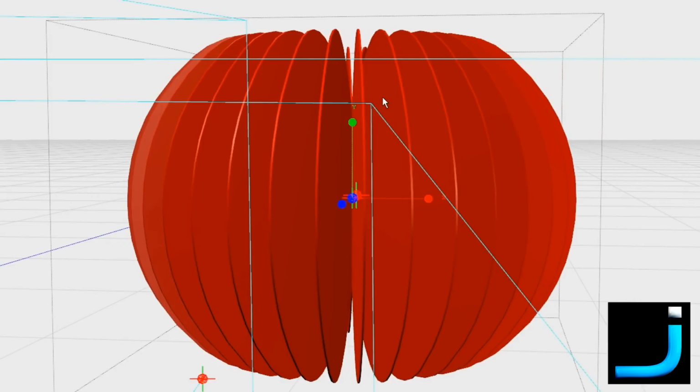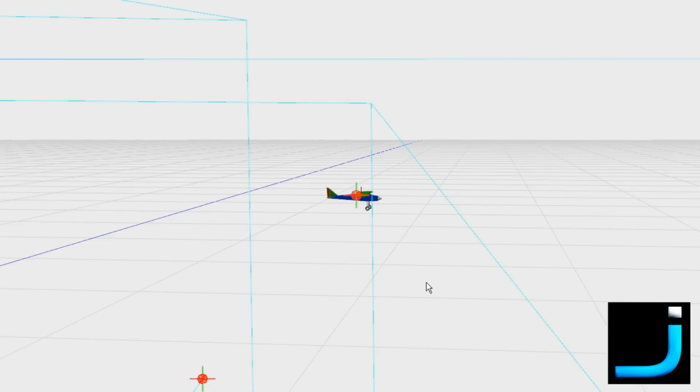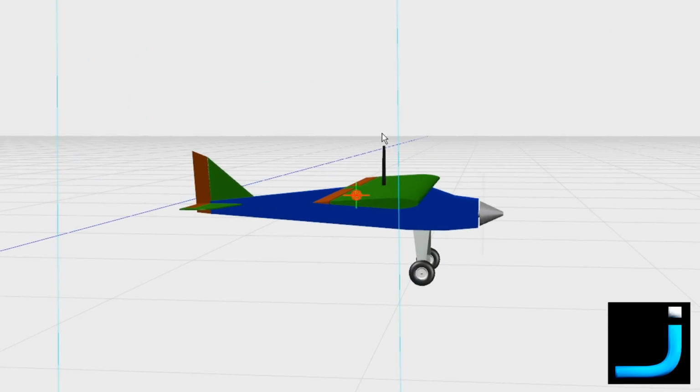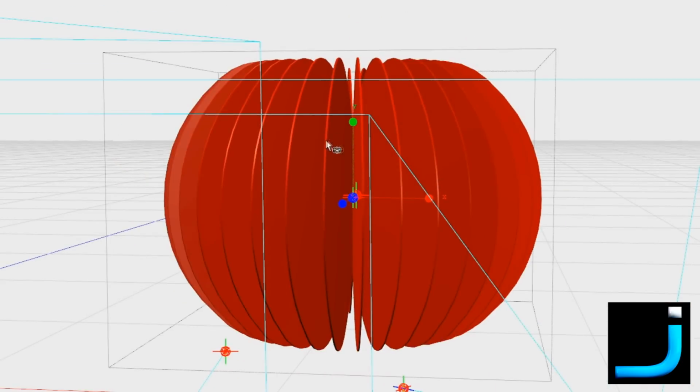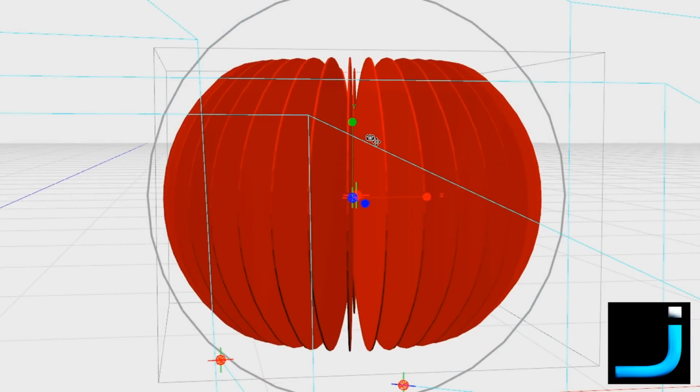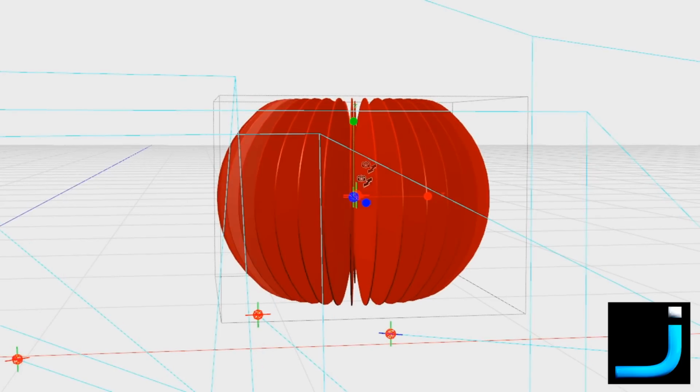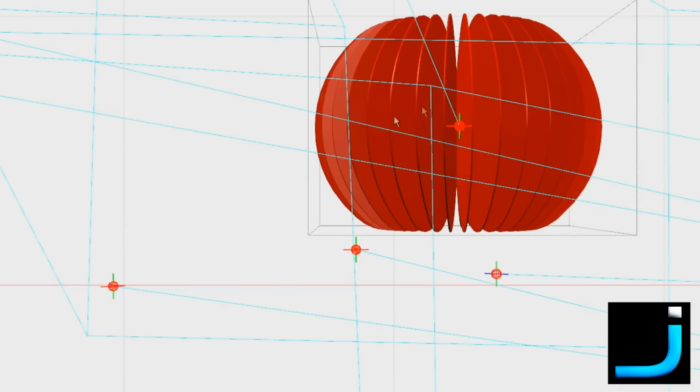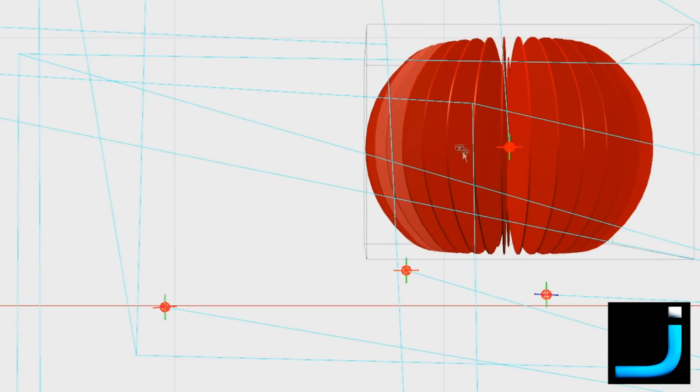Now, this antenna is a linearly polarized antenna. It's linear polarization, which means it's either vertically or horizontally polarized. That's controlled based on how we've mounted it. Because we're mounting it in a vertical orientation, we therefore have a vertical polarization pattern from the transmission. So this is our plane, and obviously we have the same antenna on the ground station. I'll switch to the front view, which is actually the side, but we'll call it the front.